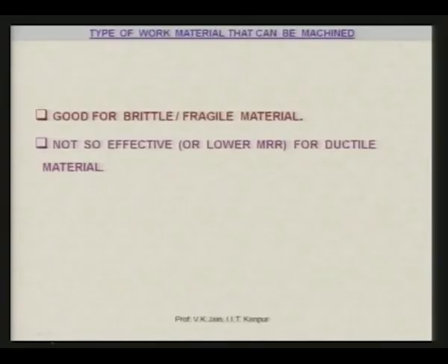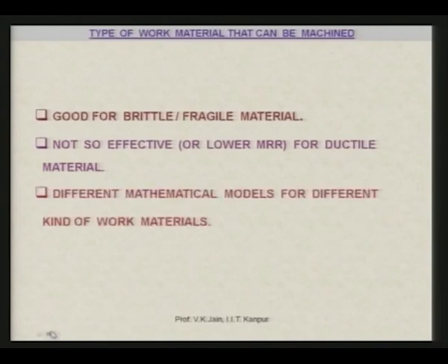This particular process, the AJM process, is good for brittle or fragile materials. It is not so effective or not so good for ductile materials, although it can be used, but it will give you a lower material removal rate.